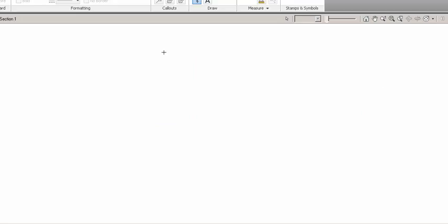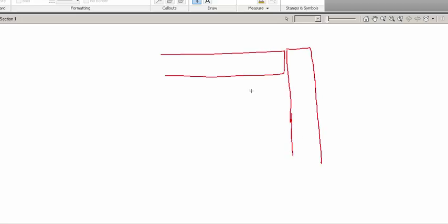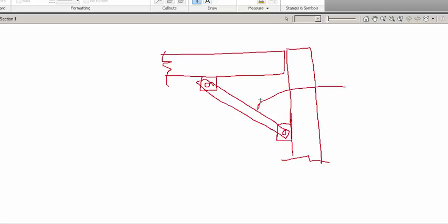For example, if we have a steel beam connected to a steel column, a lot of times we'll actually add a little shear plate right here, a little shear clip, which is a steel plate with a hole in it, and we'll put another one right here on this beam, a little break line for us, and we'll use a piece of angle to be a strut, or sometimes referred to as a kicker, to add a little extra strength to this particular connection. So the angle is used here.